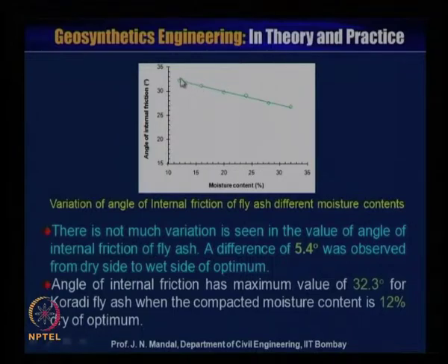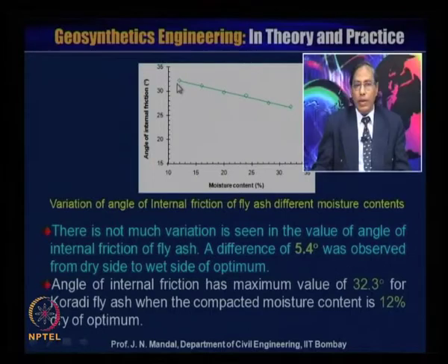Now, this shows the relationship between the moisture content and the angle of internal friction. This is the variation of the angle of internal friction of fly ash with different moisture content. You can note that there is no such variation seen in the value of the angle of internal friction of fly ash.